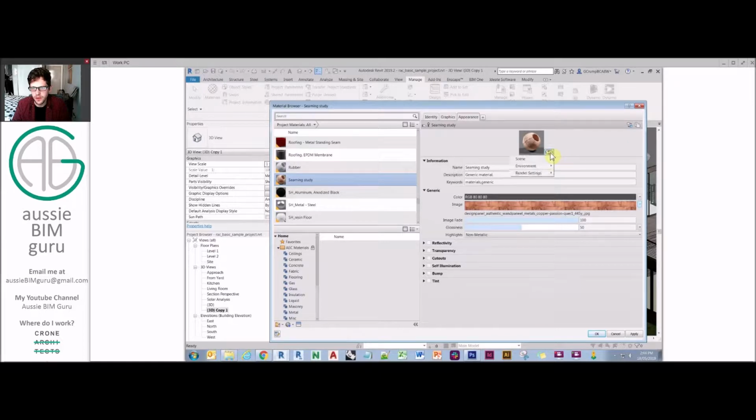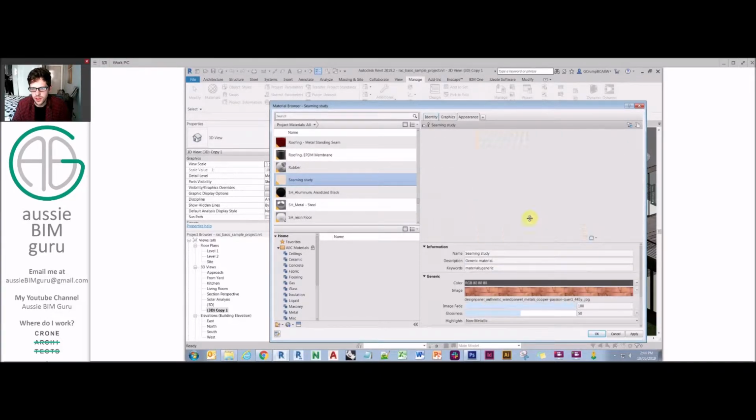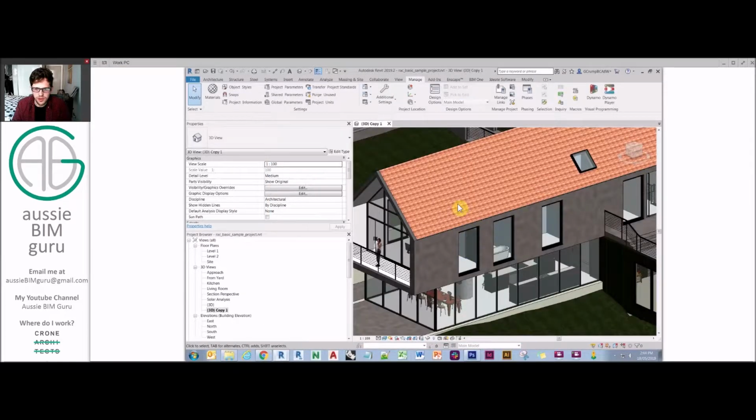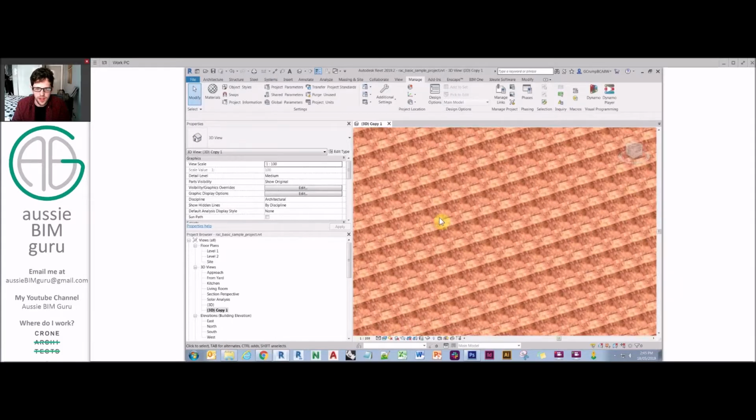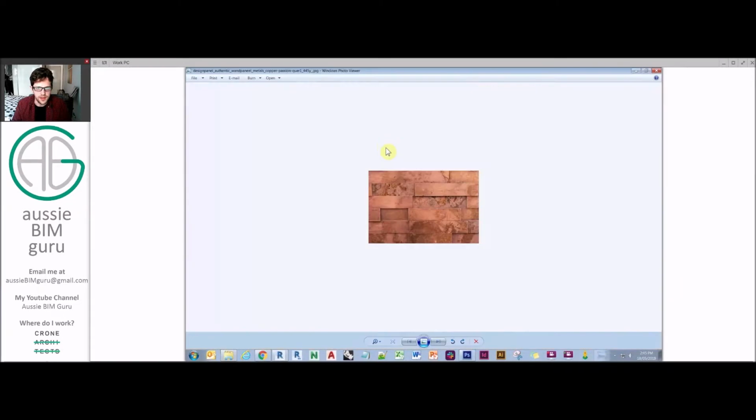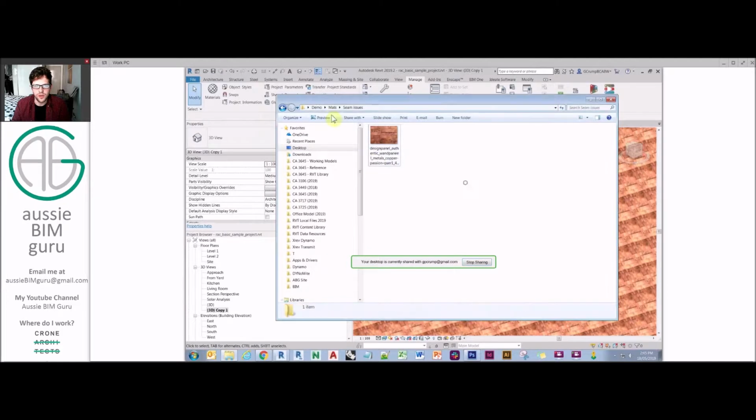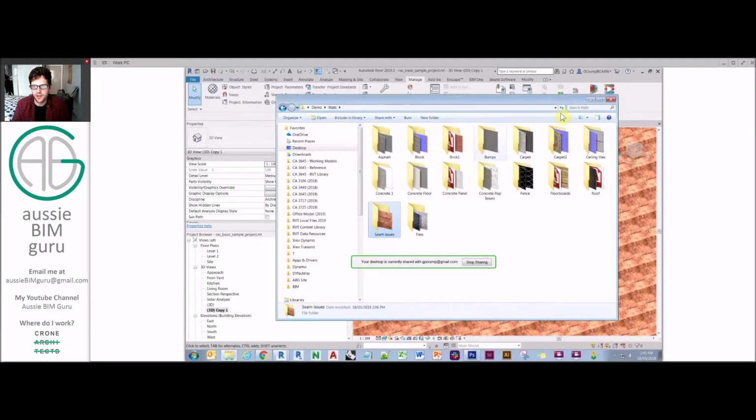There we go. So if I go to planar, you'll see that's really obvious where the material map is ending. So the material is not convincing in that you can see exactly where the shadows end. And that's really just because at the borders of the material, there hasn't been consideration paid to how this material continues. So just be mindful when you find material maps that you always need to test that to make sure.